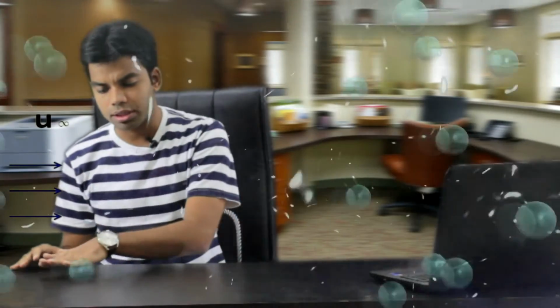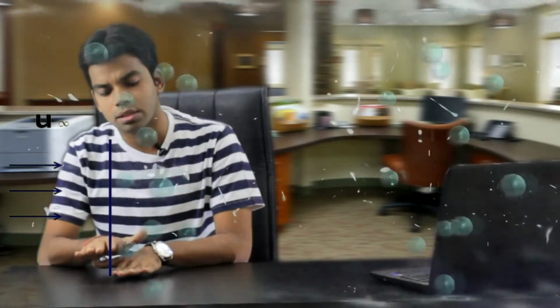Now we will understand what actually this boundary layer is. Suppose we have a flat surface and a stream of air flowing over it. The stream of air in contact with this flat surface will have the velocity of the flat surface, which is at rest, so it will have zero velocity. The first layer obviously has zero velocity, and the second layer, which is in contact with the first layer, will have a certain velocity.